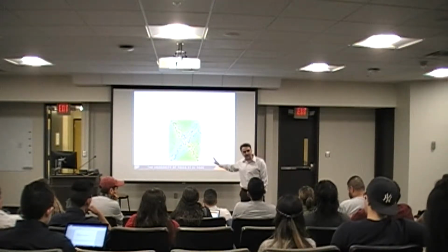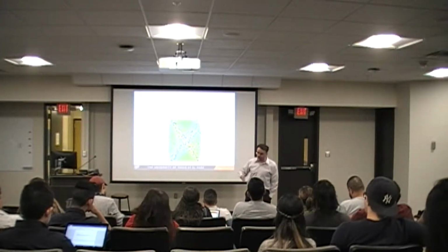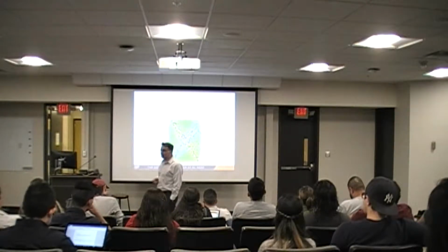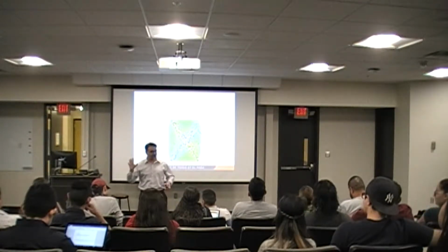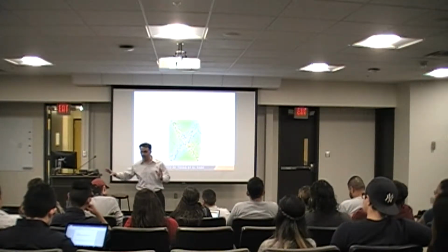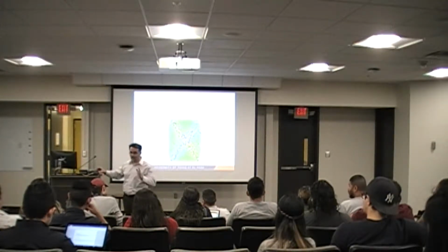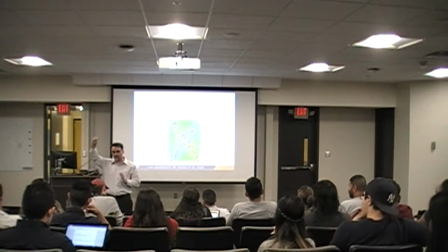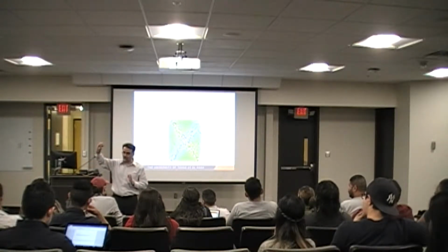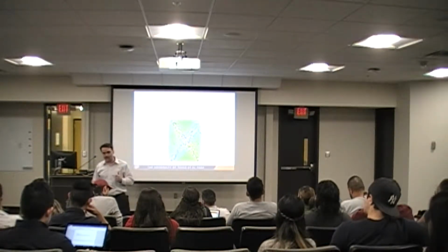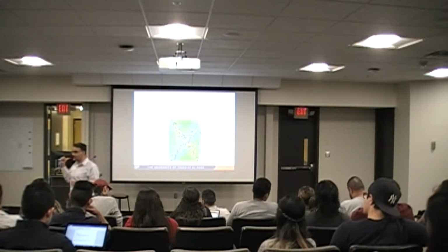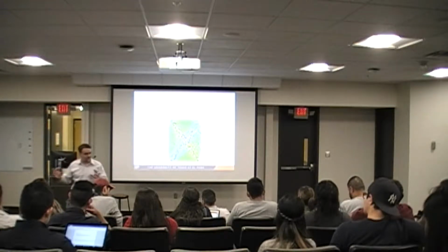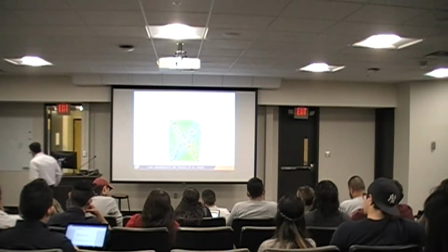So once we figure out what the strength is, our next topic is going to be settlement calculations, right? Figure out what the stress-strain curve is. On the x-axis you have strain, on the y-axis you have the stresses, and you have your stress-strain curve. The peak of that is going to be the strength of the material. So we calculated the stresses, we figure out what the strength is in this lecture, and then we figure out what the strains, or deformations, are. So this is where we're going from here.